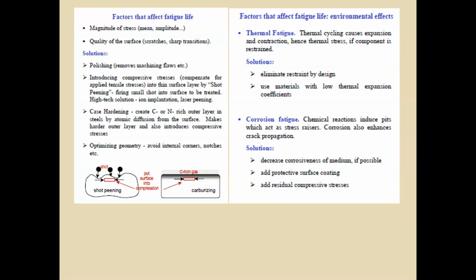Factors that affect fatigue life: environmental effects, thermal fatigue, thermal cycling causing expansion and contraction, heat and cold. Solution: eliminate the restraint by design. Use materials with low thermal expansion coefficients.